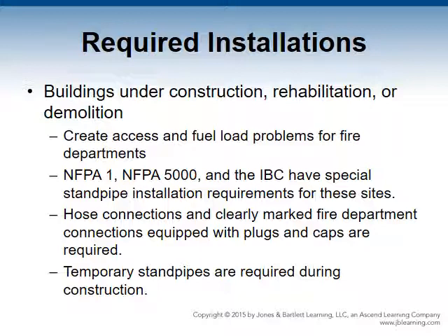There must be at least one hose connection per floor level and a clearly marked FDC at the street level equipped with plugs and caps to protect the FDC and hose valve. Standpipes must expand with each floor. Temporary standpipes must remain in place for the duration of construction. For rehabilitation work, standpipes must be on all floors below and include the highest floors where the work is occurring. For demolition, the standpipe must remain in service within one floor of demolition work.